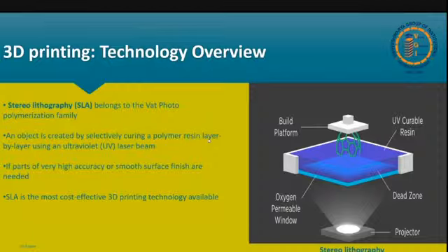And once it is done, it is turned into real gold with an injection molding kind of process called investment casting, in which the wax is placed in silica sand, and it is then heated up so that all the wax is removed and only the cavity remains.